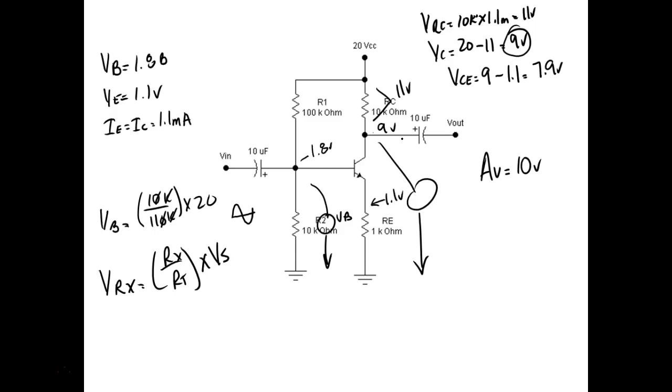You understand? So what we're saying is if I've got a resistor right here, and relative to common, which is what we're doing, I measure 9 volts on that side, and I measure 1.1 volts on that side, then how much is it going to be dropping? It's going to be dropping 7.9 volts relative to common. And that's what we're doing here, right? Y'all understand that? So all we did was figure out what VCE should be without actually measuring it.